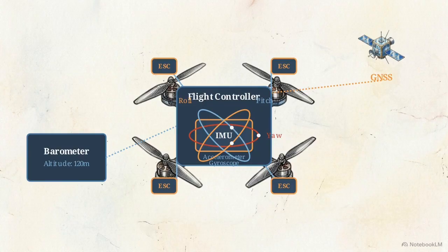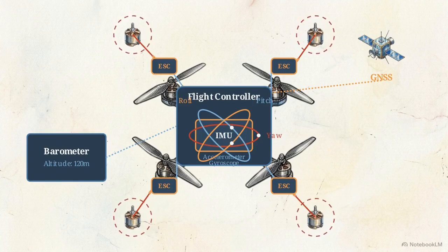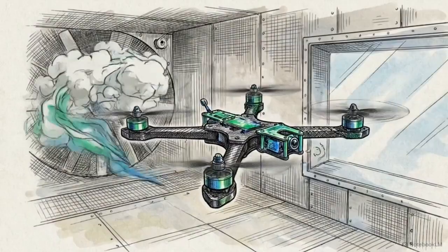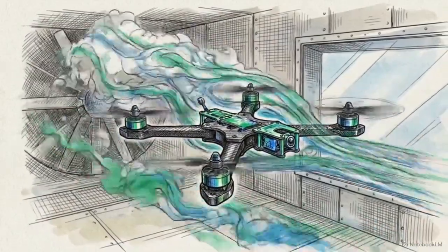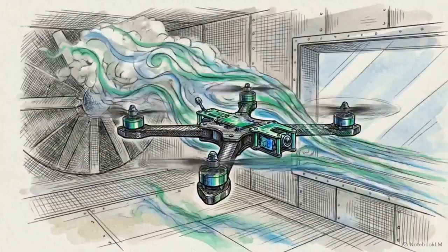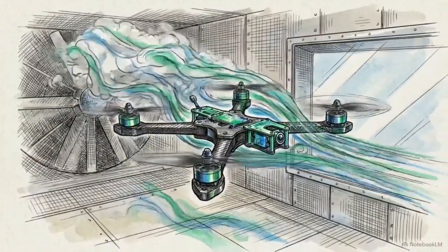During the actuation phase, the flight controller sends logic signals to the electronic speed controllers, or ESCs. These modules translate those signals into precise electrical currents, driving the exact RPMs needed at each motor to maintain the desired flight path. This universal closed-loop avionic stack standardizes uncrewed flight. It provides the mathematical stability necessary to control even aerodynamically unstable frames through software algorithms.